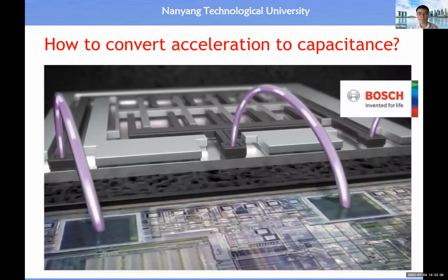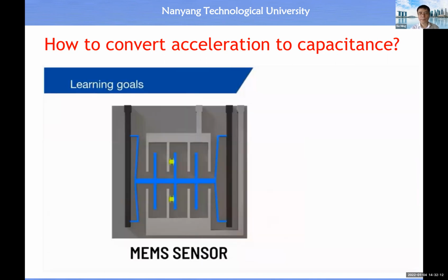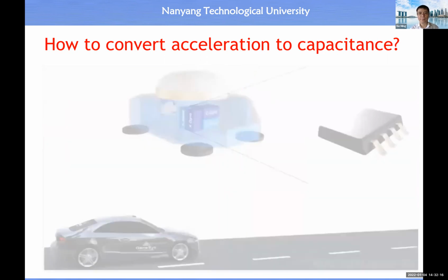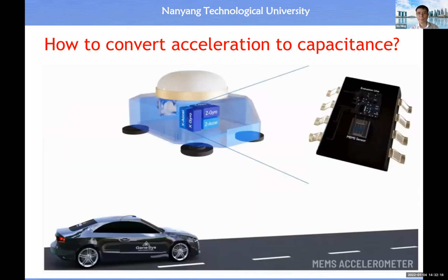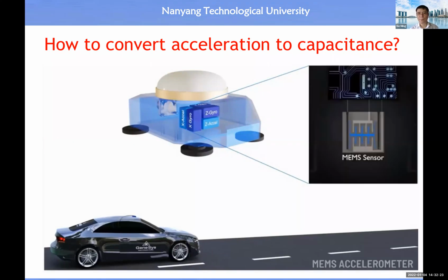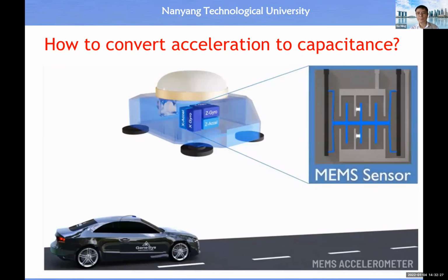This video shows the function of MEMS accelerometers, which are integrated in our ADMA systems. The MEMS sensor consists of an evaluation unit and a micromechanical comb structure. These combs are creating capacitors whose capacities are defined through the distances in between. The blue marked comb is set in vibration with a specific frequency.